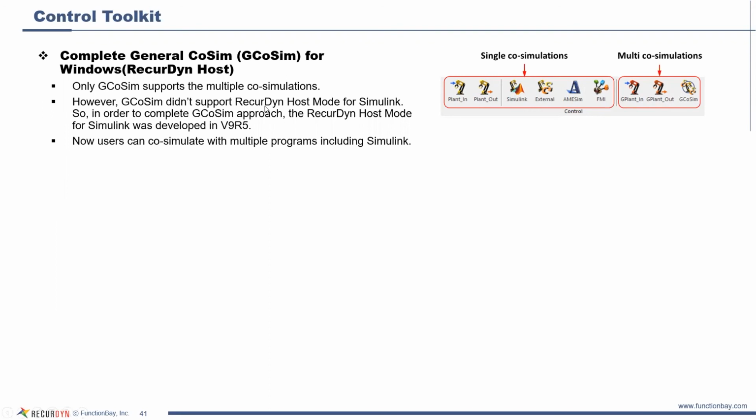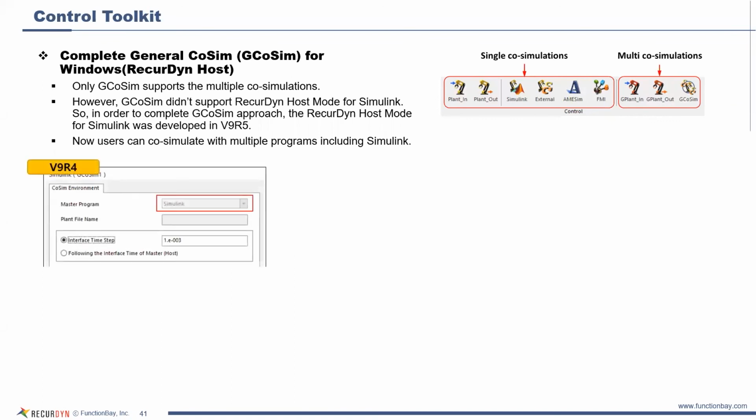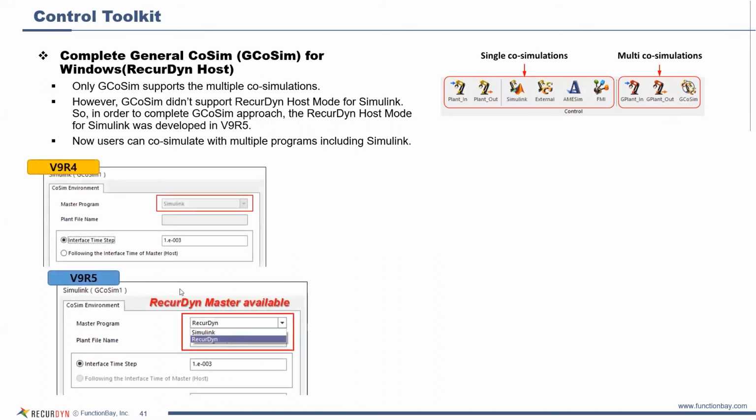In the past, the general CoSim didn't support the RecurDyn host mode for Simulink. But now that it does, when users co-simulate with multiple other softwares, Simulink can be one of those softwares. So that's showing that RecurDyn is now available as the master program here.